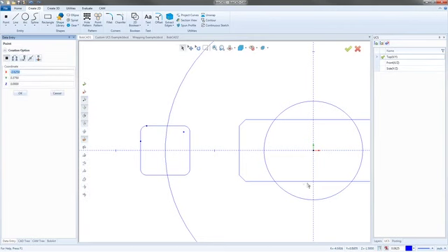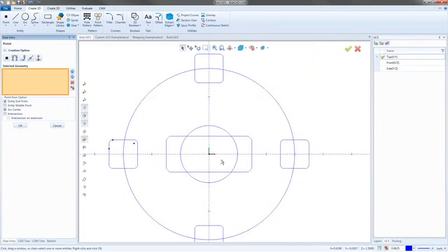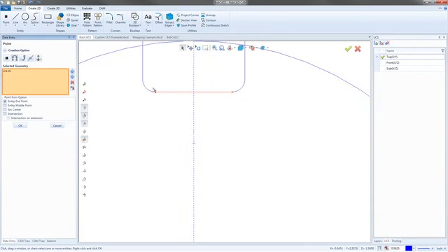Your coordinates are going to work the same way. They're all based off of our main coordinate system here. So just type in exactly where you want to put the point, and that's where it's going to go. Right here, we have a point from entities. Now, this has a few functions on it. If you want just a single endpoint, I'm going to uncheck the arc center. If I just want an entity endpoint, what you'll see is if I click on this line, I get two previews for a point there and a point there.